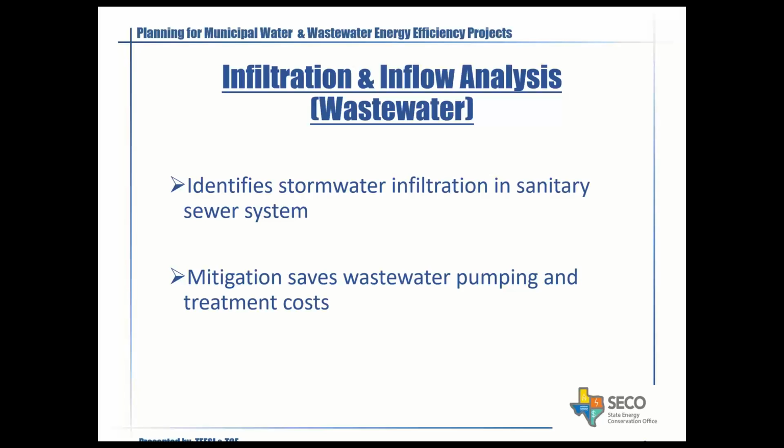But when you can identify your stormwater infiltration and inflow, you do not have to pump that water. You can mitigate it, and you don't have to treat it. So just keep in mind, just a simple I&I study can save lots of money and lots of power.